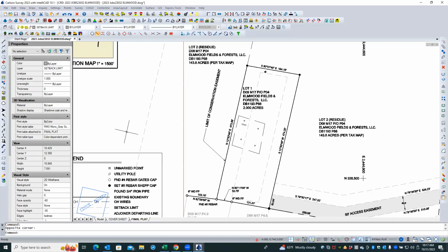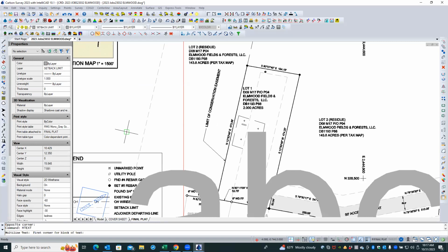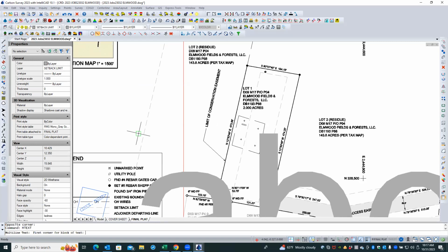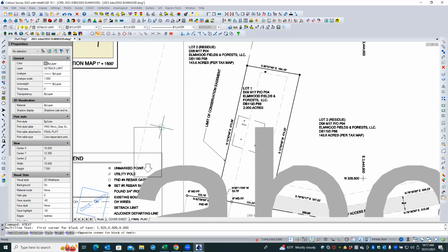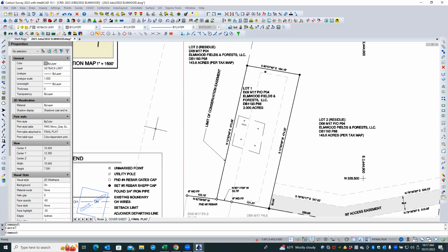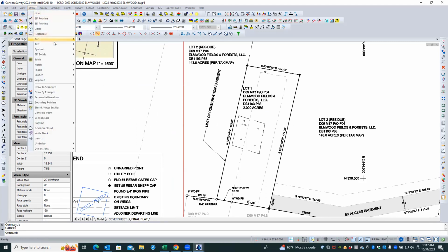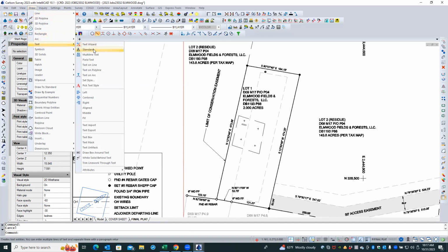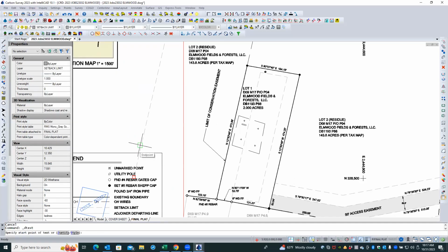You could just draw text, just plain old standard text. If you chose, there's your start point, and let's make it 0.08. I'm in paper space, and the rotation angle is E. So that should be right, because my UCS is now lined up with that line.